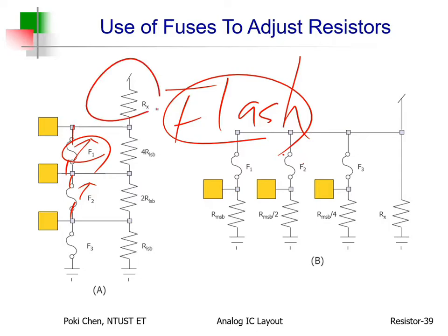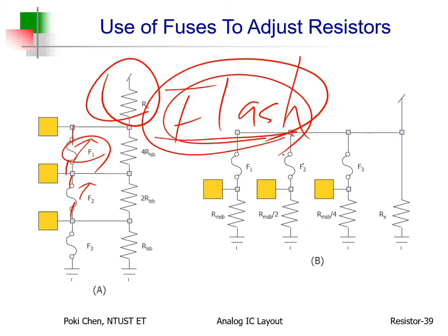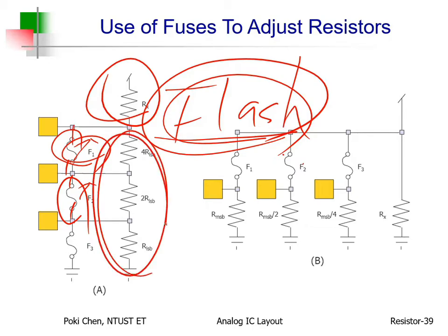So after measurement, you can make the decision to turn it on or off, then store the calibration value into flash memory to keep the on and off state for all those calibration resistors. Bingo, that's it. Very simple idea, right? That is the current methodology to deal with calibration.